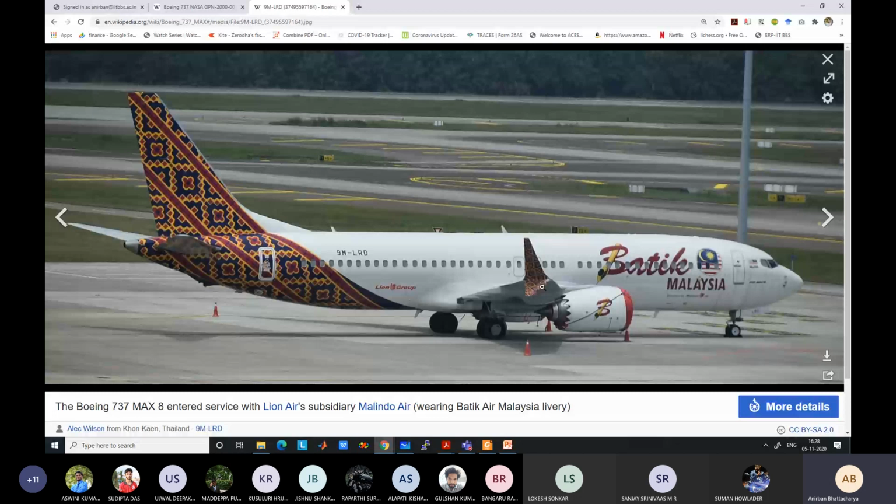Okay, now as a side effect of this, in certain cases when you actually want the plane to dip forward, because the pilot wants it to for some reason, the autopilot was not allowing the pilot to do it. The autopilot thinks the plane has become unstable, so it wants to go back to some position. As a result, a feedback reaction occurred, and the flight stalled. It went to such an angle that no lift was being generated, and the flight crashed.